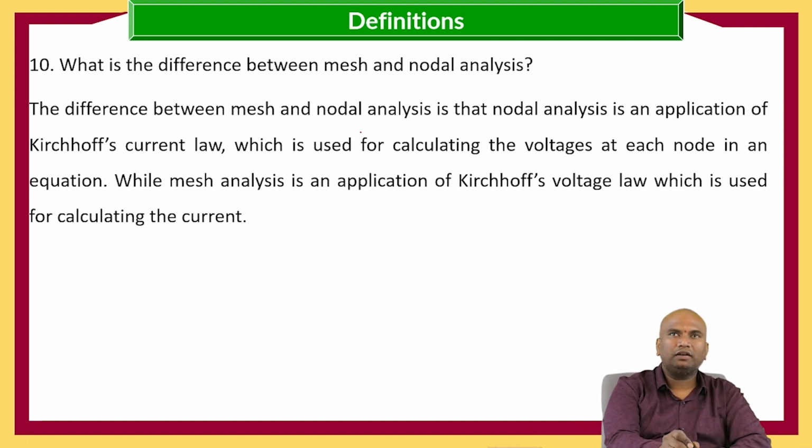The difference between mesh and nodal analysis is that nodal analysis is an application of Kirchhoff's current law, which is used for calculating the voltages at each node in an equation, while mesh analysis is an application of Kirchhoff's voltage law, which is used for calculating the current.